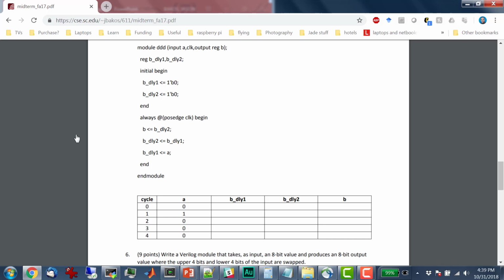Well, you would think it should be the old version no matter what because it came first. I referenced that before I set it. But it's Verilog, it's concurrent semantics, so there's no guarantee of that. Actually, now that you mention it, I'll have to test this out. I don't know for sure, but it could be the case that if I had used just blocking assignments, then this whole thing would have collapsed down into one cycle of delay, right? Because I would change B delay 1, and then this line of code would see the new version, not the old version,